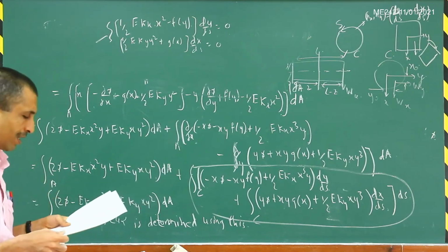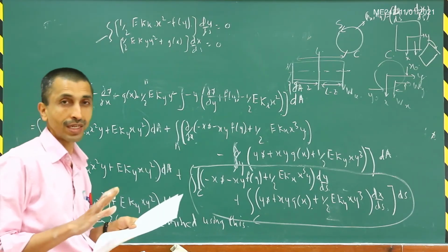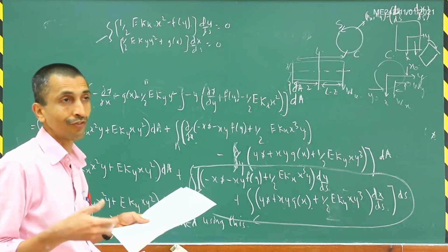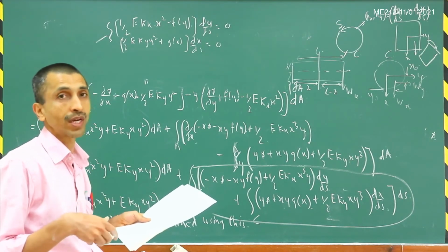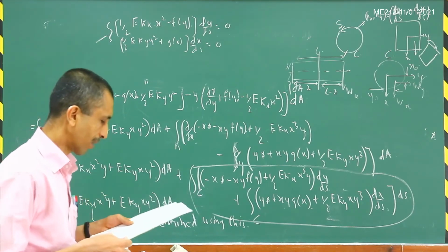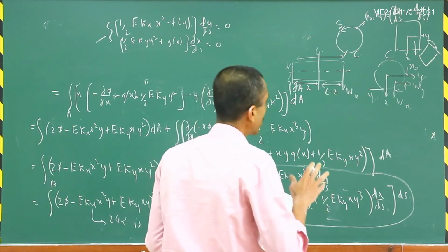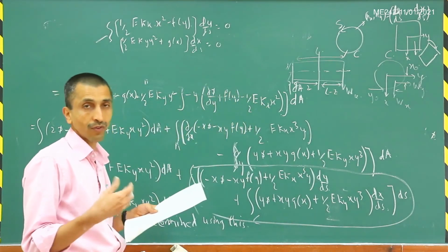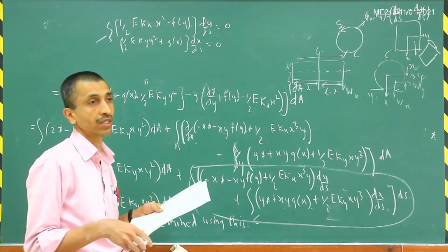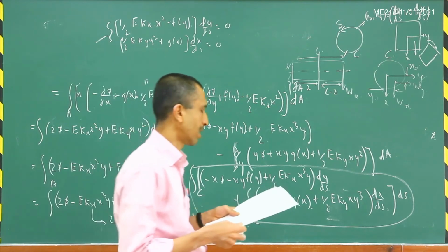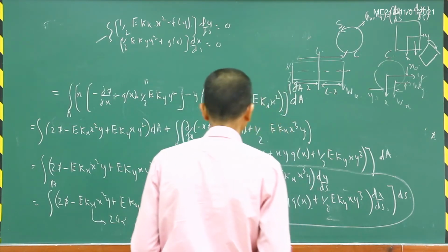So that way we can solve now for the entire function phi, and once you know the function phi, then you can find out the stresses tau xz and tau yz. Okay. So that is the procedure. We will illustrate this procedure on certain types of cross sections, such as the elliptical cross section or the rectangular cross section at a later stage. But at this stage, let us just continue this particular discussion.